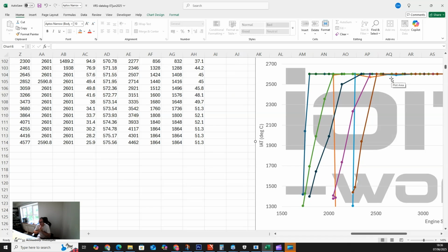But I had a lot of issues maybe 10 years ago tuning hybrids where I would go in, we'd set the actuator, we would tune the duty cycle in the N75 map, and then with the customer we'd do data logs again, and you'd see basically the system was struggling to make pressure where you wanted it.